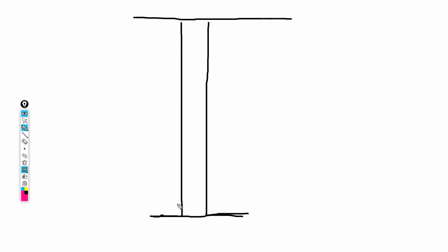So those links, they are going to be provided at a given spacing. Okay. So we take this to be a support region, and also this one to be a support region. Okay. They are called confinement zones. We have 3 confinement zones, be it in a column or be it in a beam. Okay. So near support, this is the first confinement zone.